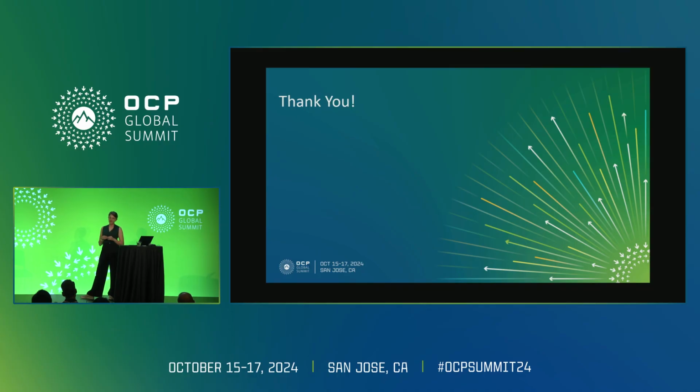Back to your question, there's a little bit of both. So as far as the activation energies, you can't create a new activation energy because every new equipment and fluid combination is a new chemical reaction. And so it would be incredibly inefficient to create activation energies for accelerated life testing for every single combination out there. So we have to think about things a little bit differently. And as far as the electrochemical, that's why we have to do testing at the component level. So when I said component reliability, that's when you're going to go more towards understanding what the actual reliability of a component is as far as its use case lifetime.